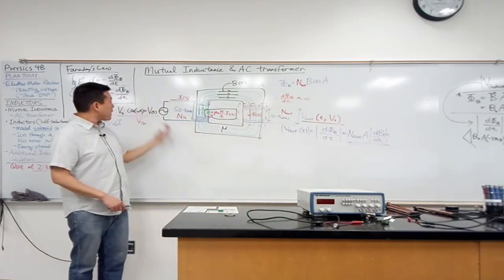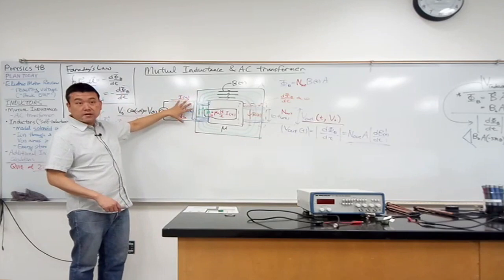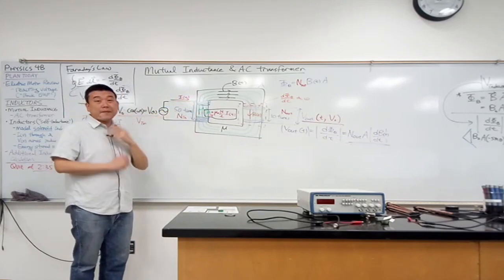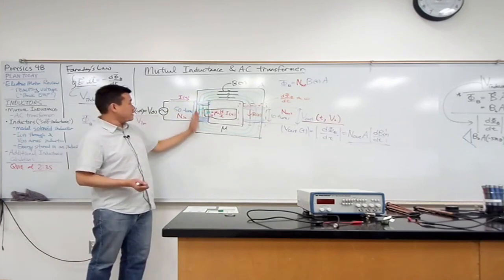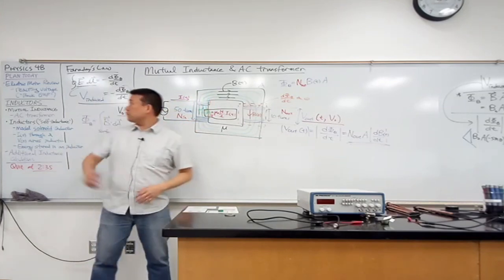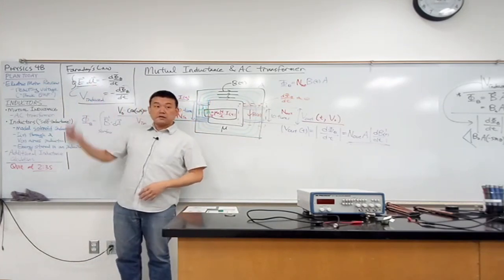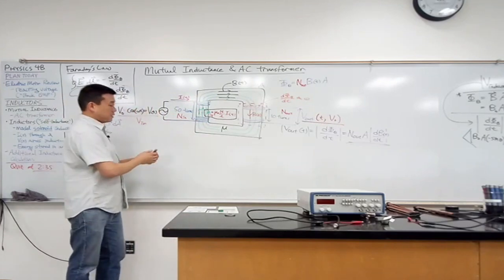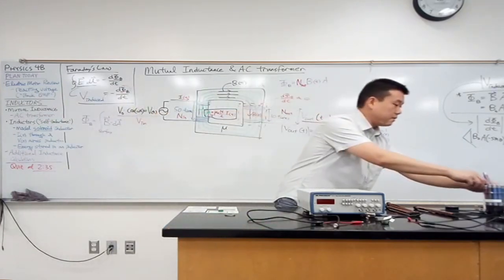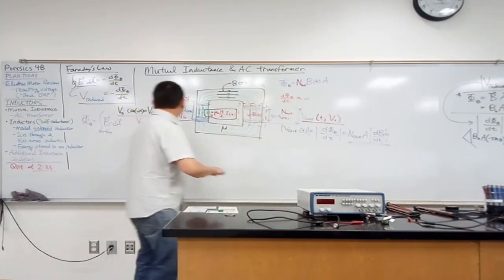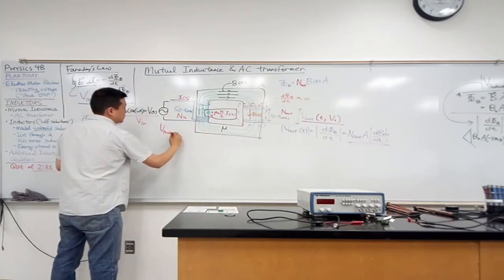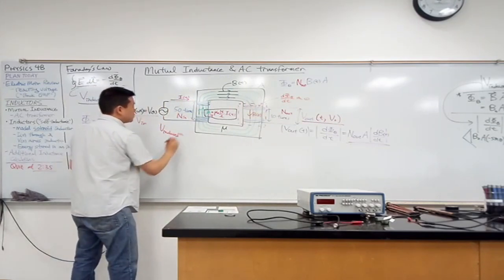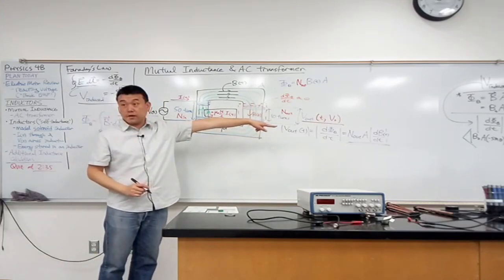We look at, all right, so what's the voltage here? And this is the part that will look a little bit backward, because I'm going to do the same thing here. I have the magnetic field, and I'm going to go through Faraday's law and say, induce the voltage here. Let me write it down. The induced voltage here, V induced, is equal to what I just went through there.